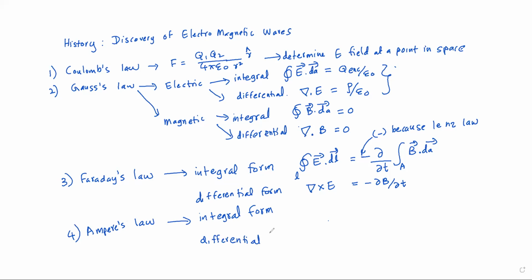Similar to Faraday's law, we can write the total magnetomotive force generated as an integration. We write L in here to show that the magnetomotive force is generated at the edge of the surface, and it is caused by the charge density that is available in the surface, and the rate of change of electric field across that surface.